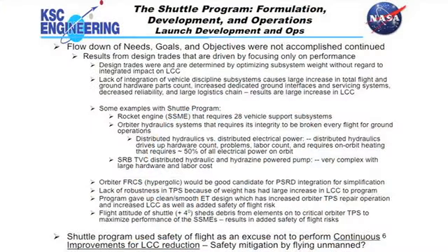The orbiter hydraulic system is a distributed hydraulic system. And one of the choices in that, because we didn't want to fly the weight of hydraulic fluid in a line that runs from the system to the main landing gear, requires us to go in and break the integrity of that system every time we fly. We have to go in with a ground system in order to operate the landing gear. So you can't leave that system intact. Again, that requires additional servicing and additional hardware.